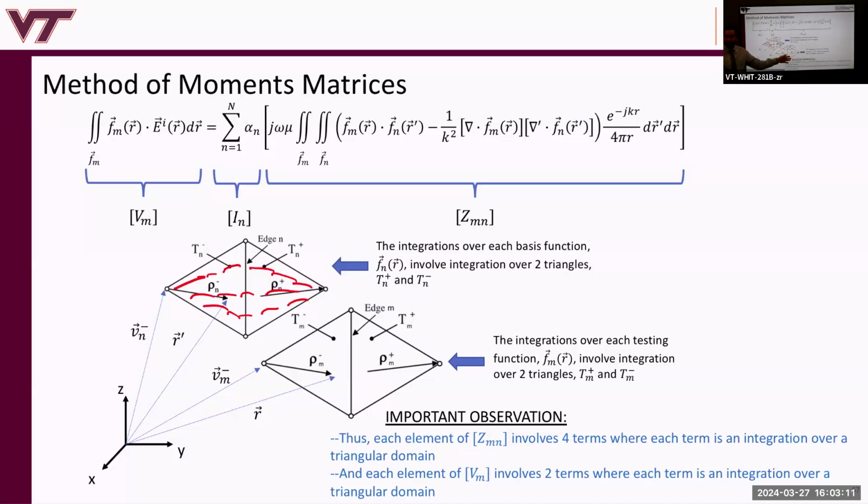We calculate the radiated electric field due to the current that's supported by both these triangles through the use of the Green's functions, right? And then we observe that electric field over these two triangles, and we take the functional inner product with that electric field scattered or radiated by this current as observed with this basis function or this testing function and integrate, right? Okay.